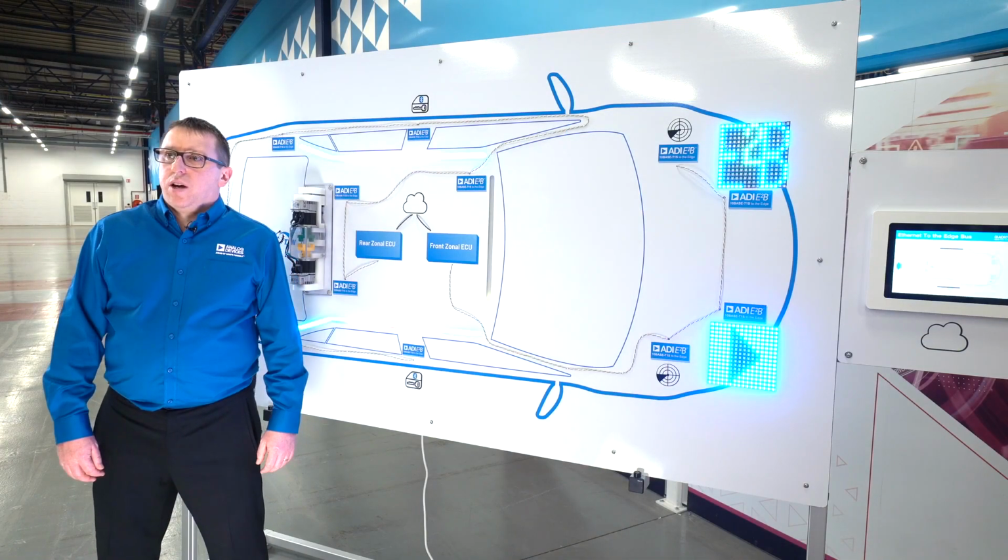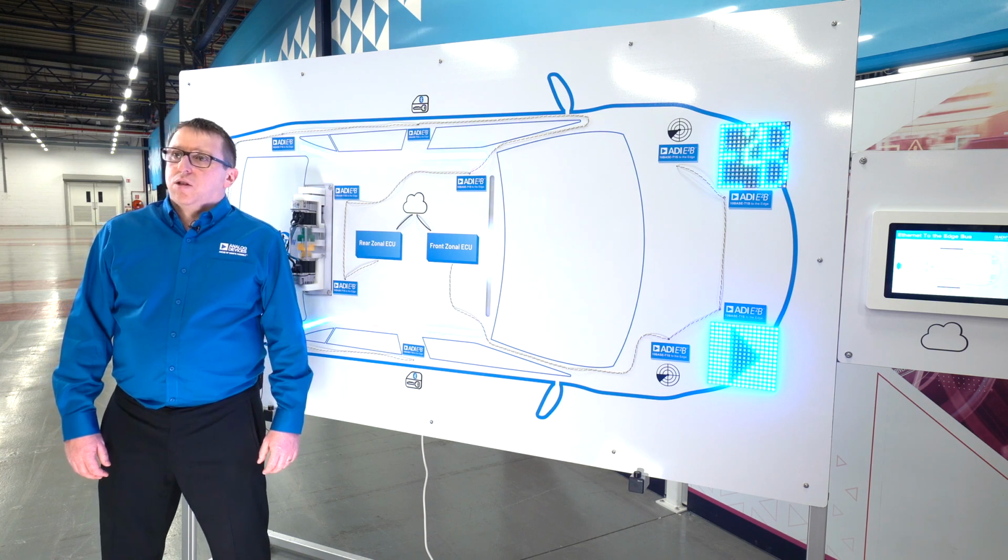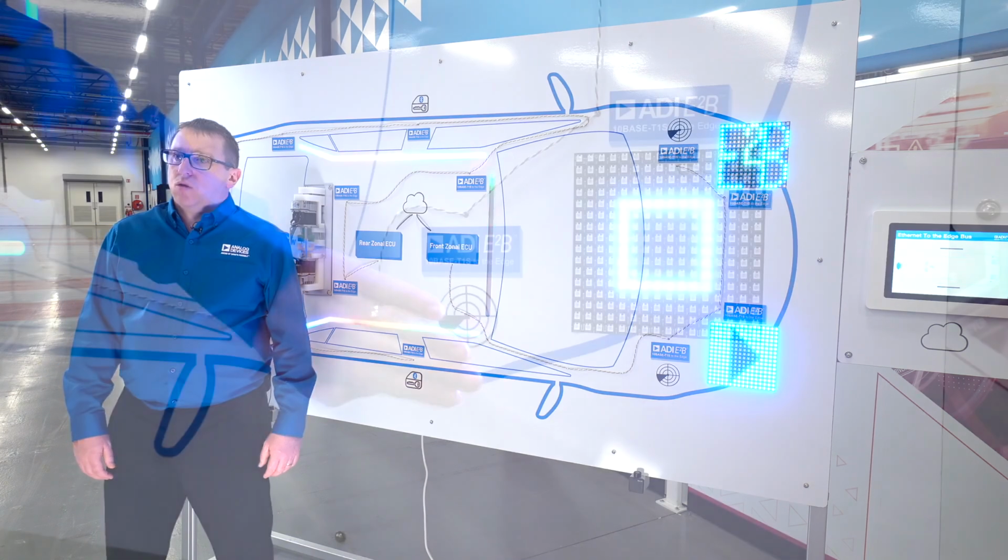Physical layer collision avoidance (PLCA) is implemented on the 10BASE-T1S network to maximize data throughput, and as the name suggests, avoids collision and thus preventing the need for retransmitting data. This can be observed with the radar sensor and the LED array, which are demonstrating a low latency control loop.